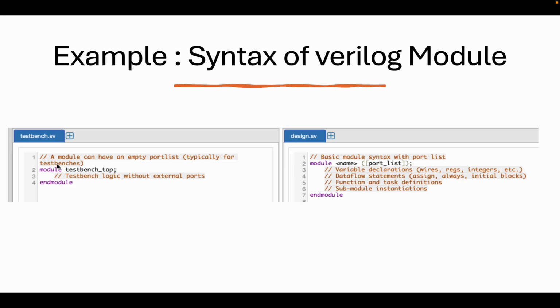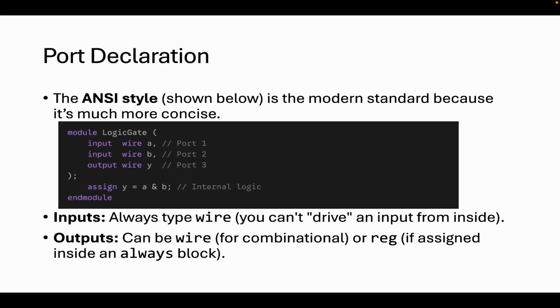In a similar way, we'll also use it for the test bench. You write the module test bench and the test bench logic, whatever input you will be giving, and what output is going to come, you can verify it. After the simulation you get the waveform, right? In that you can verify it.